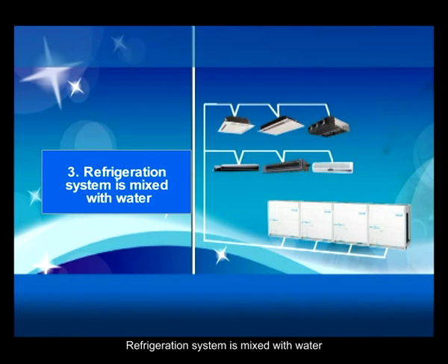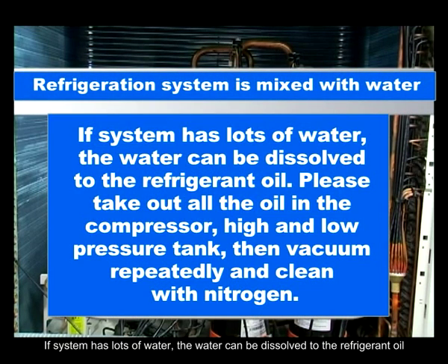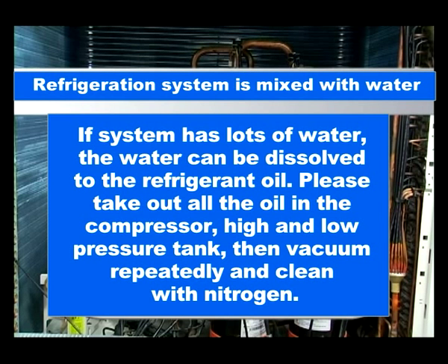Refrigeration system is mixed with water. If the system has lots of water, the water can be dissolved into the refrigerant oil. Please take out all the oil in the compressor, high and low pressure tank, then vacuum repeatedly and clean with nitrogen.